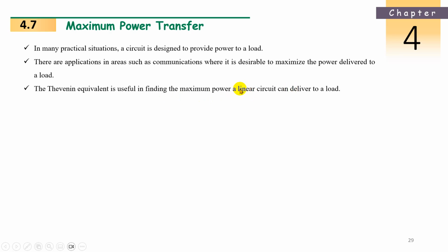It is easy because in Thevenin's, the voltage source is in series with the Thevenin resistance and the load, so all are in one loop only. In Norton's, there will be two loops, with the source current, the Norton resistance and the load resistance, so the calculation will be bigger than Thevenin's. So let's go with Thevenin's.